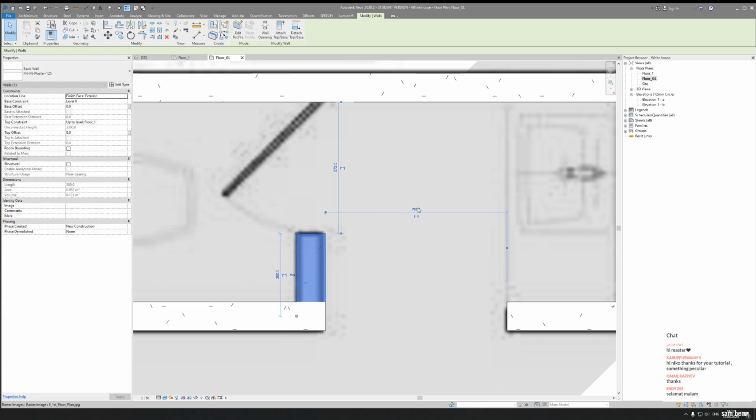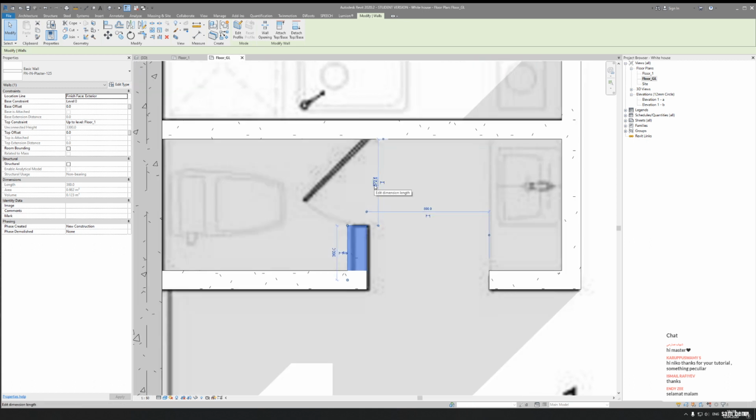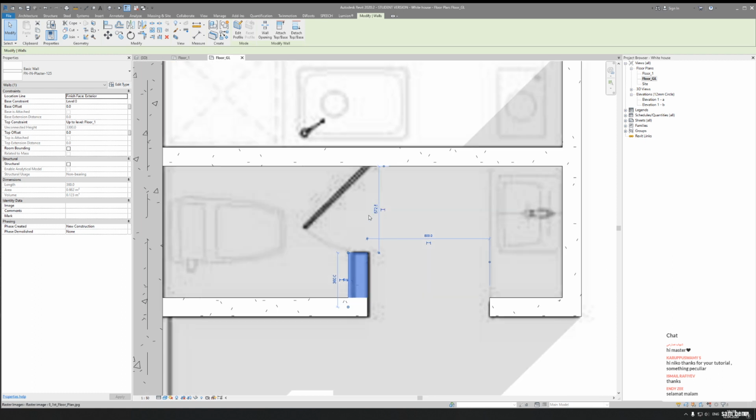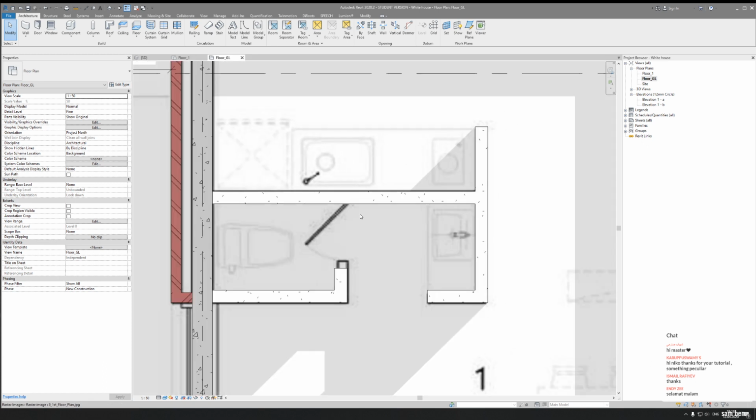So we have here the opening. Actually, 780, this is a bit small. Let's make 800 millimeters, this is enough. And this opening, like 500 millimeters, it's really thick. I don't know, maybe for Japan standard it's okay, but actually if you try to get in through a 500 millimeter opening, you will not. So let's change to 650 millimeter at least. I know this is not following the standard, but 500 millimeters is so small.